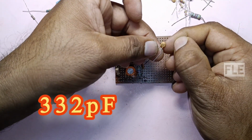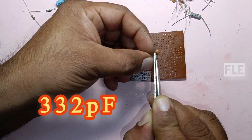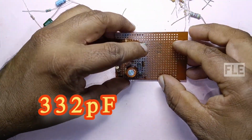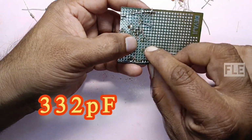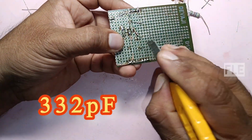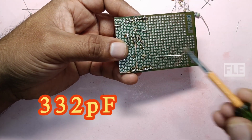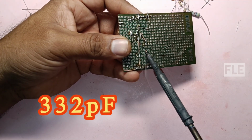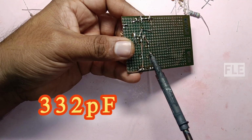The 332 pF capacitor: one end is connected to the negative terminal of the 2.2 microfarad capacitor. The other end of the 332 pF is connected to the first terminal of the treble controller. The 2.2 microfarad negative terminal is connected to both the 10K resistor and the 332 pF.